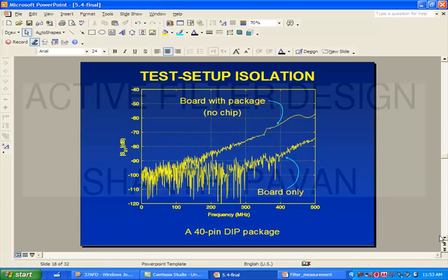That makes sense because induced currents are all proportional to frequency, correct. Now for example at 400 megahertz the isolation of the package is only about minus 65 dB. In other words, if you took 2 other pins on the package, which were not connected intentionally, just through RF coupling at 400 megahertz, if you put in a volt here you will pick up a millivolt there. You understand?